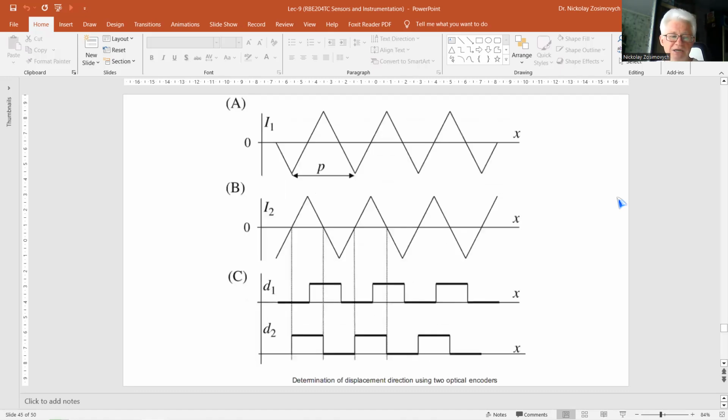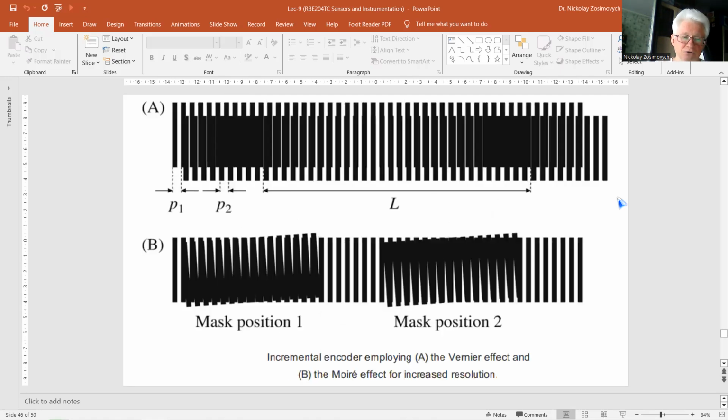Note that the measurement head of a commercial incremental encoder may contain 4 masks to obtain direction sensitivity. According to this figure, zero crossing accuracy, as in the previous figure, and interpolation all in one. This mask serves for detection of the reference markers. So the intrinsic resolution of an incremental encoder is set by the number of slots per unit distance or rotation.